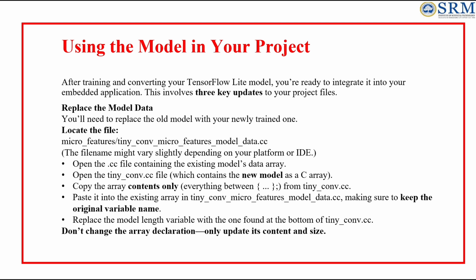Next, open the tiny_conv.cc file, which holds the new model represented as a C array. Copy only the array contents, everything between the curly braces, and paste it into the existing array, and keep the original variable name. Finally, update the model length variable with the value from the bottom of tiny_conv.cc. Don't change the declaration itself, only the content and size.